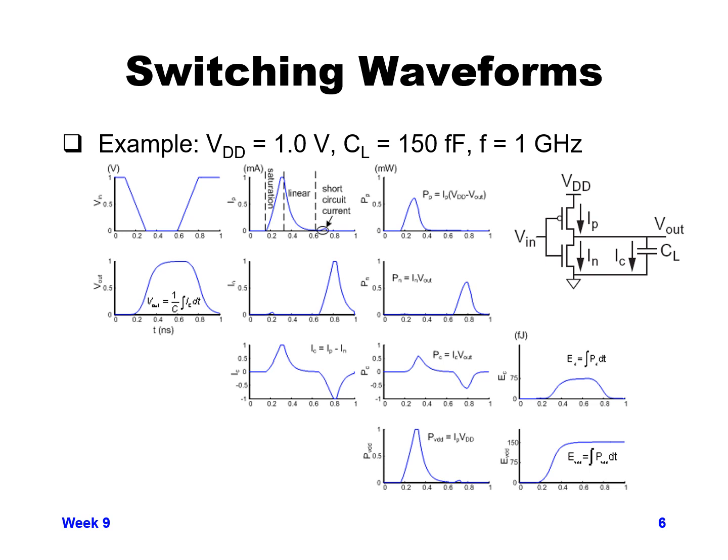Keep in mind, the capacitor stores charge and stores energy, but you've consumed everything that you're going to consume from the power supply when you charged up the capacitor. When you're discharging the capacitor, it doesn't require any current or any energy from the power supply anymore.